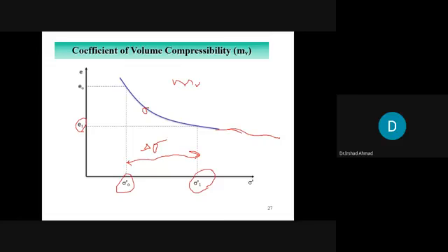What would be the stress caused by the structure? So in such a case, British code says that you take delta sigma equal to 100 kPa, which is roughly equal to 1 ton per square foot. 100 kPa.